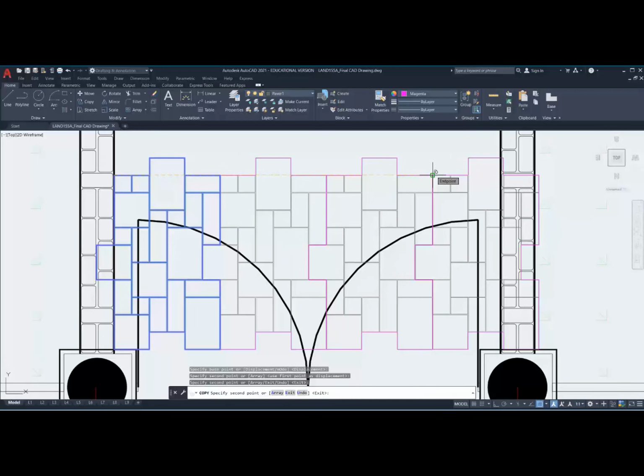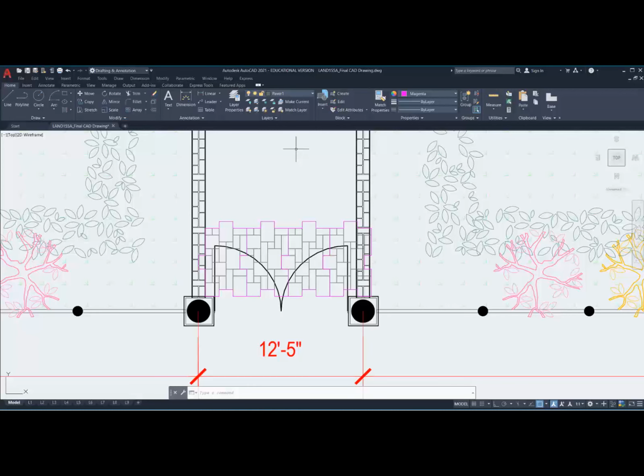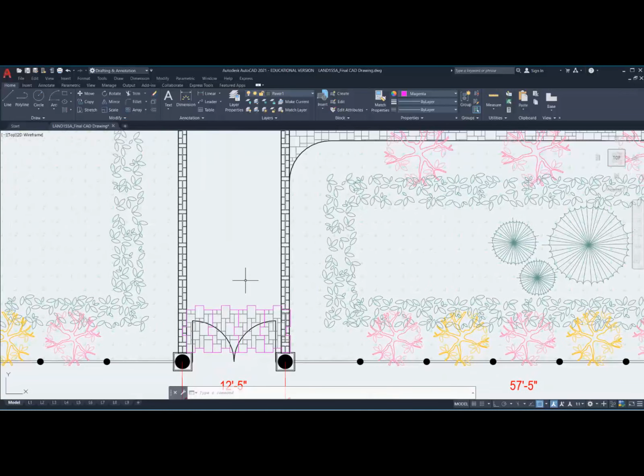Now, you have a number of different options here. If you know the tiles you're going to use, you can actually change the width of the project to match the tile pattern. And that's a very logical thing to do, because then it works. And that's really what you can do in this particular example, so that as I tile it through the project, it fits perfectly in the project. And that's what you want to do, is not have cuts.